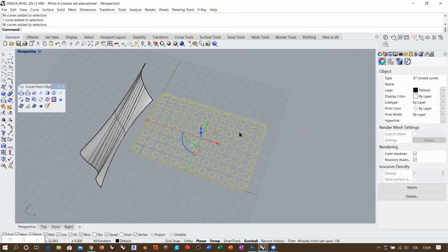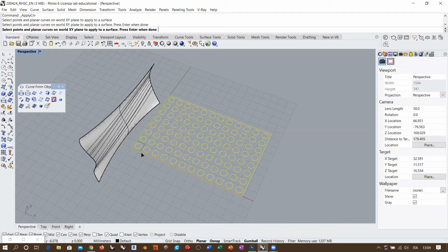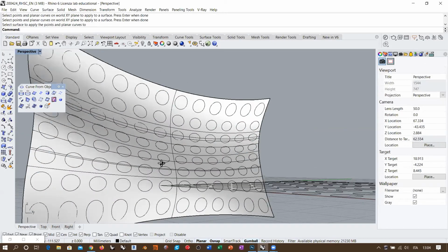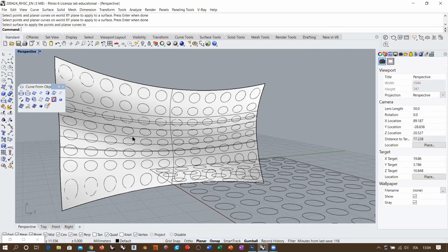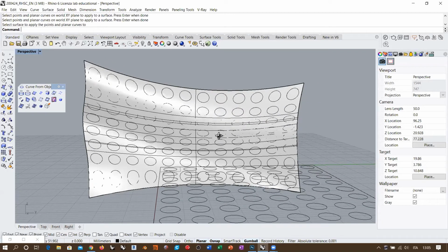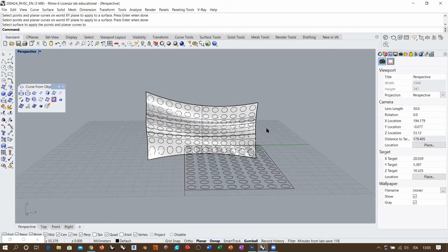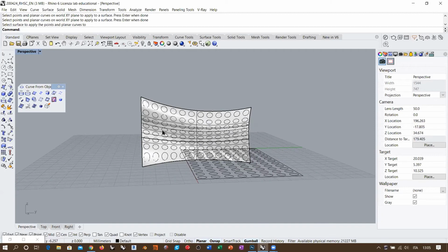And I want to apply UV curves, which are this plus this, onto this surface. Now, I get this distribution of circles, but you see that I have ellipses, vertical ellipses, horizontal ellipses, and this is due to the speed of this surface vertically. Because from the longitudinal aspect, we have a smooth, even distribution of spans, because we were using only 1, 2, 3 cross sections, which are more or less with the same separation. So you see that the width of this circle is not changing, but the height changes according to the topology.